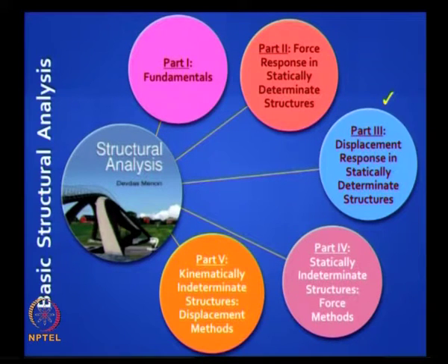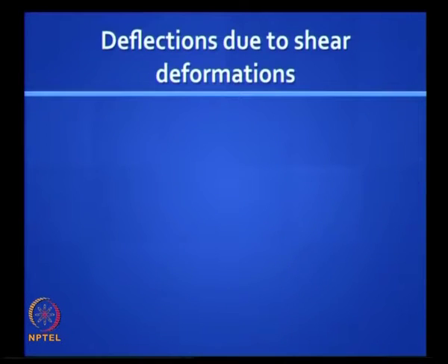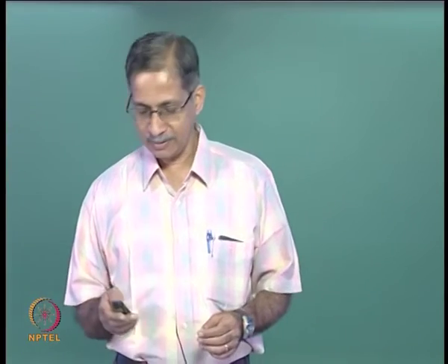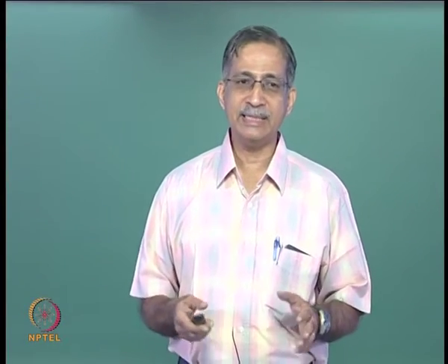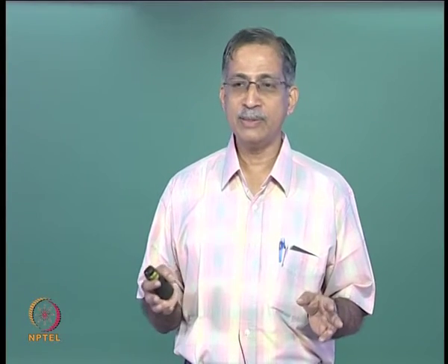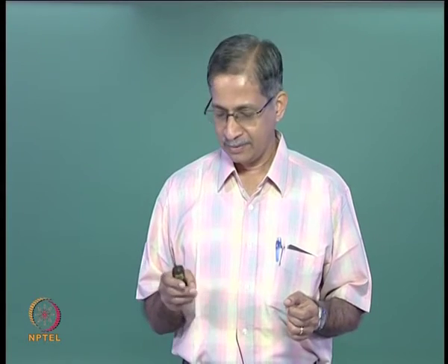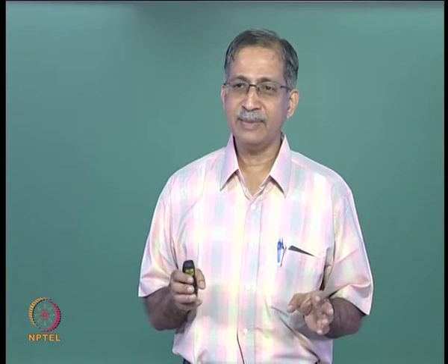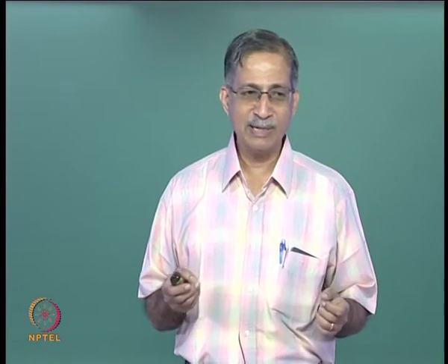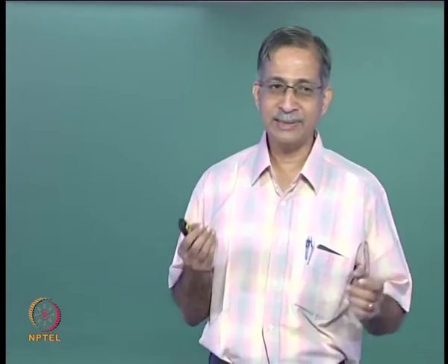We are referring to this book on structural analysis, and this portion is covered in part 3 of that book. If you recall, we ended the last session with a popular theorem in energy methods, which says that the external work on a structure is equal to the internal strain energy. Now, the use of that theorem is limited to finding unknown displacements. Why is it limited? It is not versatile. What is the limitation in the use of that theorem?